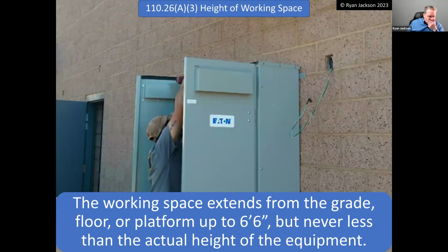Here's what I want you to think about. You need to basically be able to take an empty refrigerator box, put it in front of your equipment, right? Your panel board, your switchboard, your switch gear, potentially your transformers, depending on the installation and what size the transformer is, right? Whatever is likely to be worked on while energized.